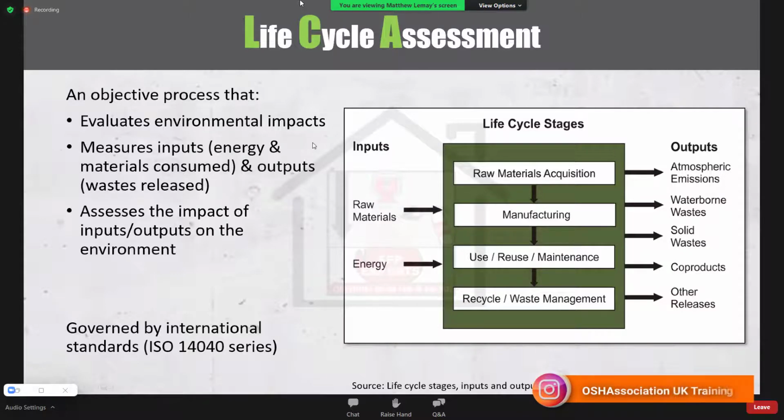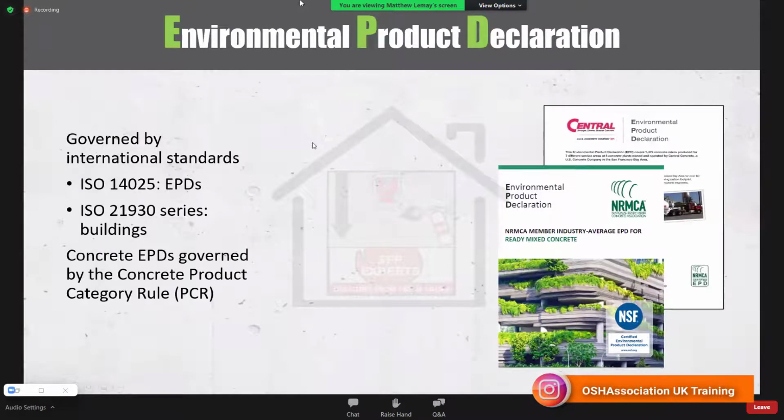Now on to EPDs, or Environmental Product Declaration. That's what EPD stands for. This is a companion to LCAs, which comes afterwards. An EPD is a communications document, which communicates the findings of an LCA to a third party. That third party could be a contractor asking for environmental impacts in the spec. That could be a certification program like LEED, or it could be a government regulatory agency. My colleague Katie later in this presentation will go over some of the different use cases for EPDs.